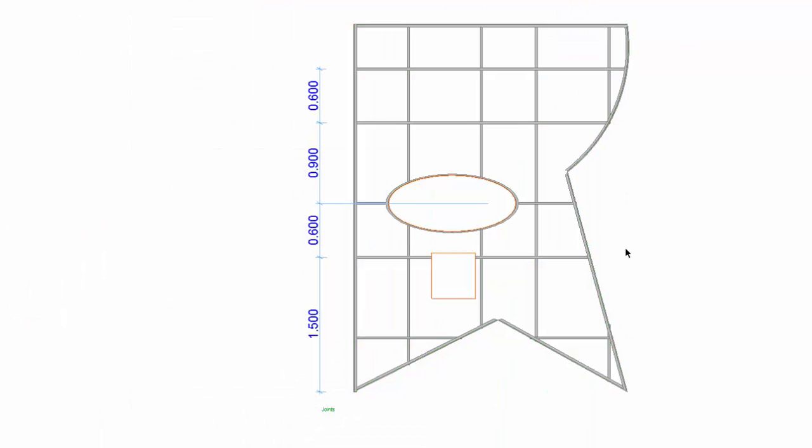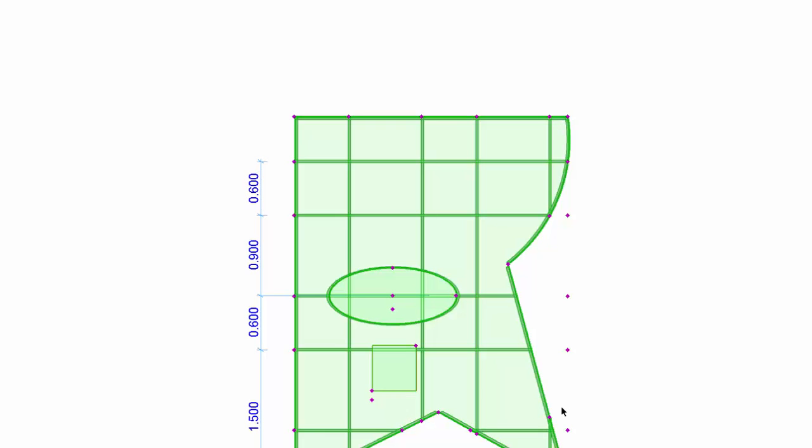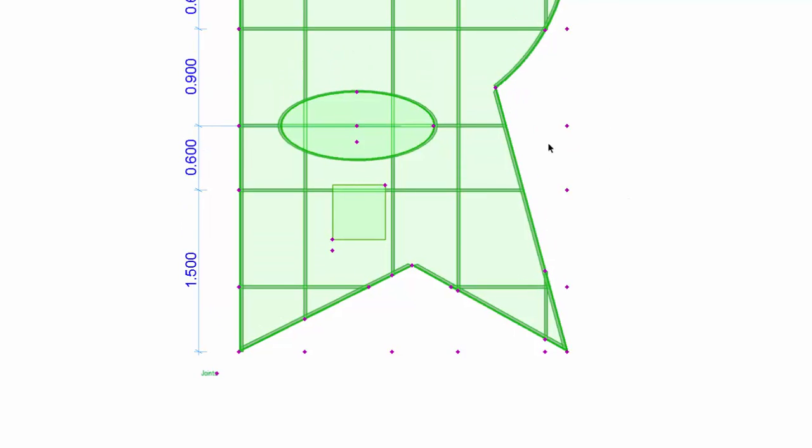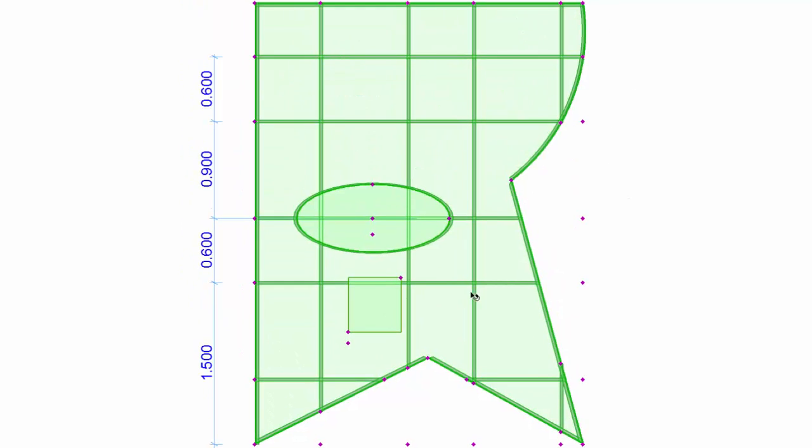Okay, so what was happening with that issue, this is something that you have to be wary of, is when a joint is running into two edges at the same time, it basically computes a cut twice at the same value, and that obviously causes problems. I'll have to try and work out something to work around that, because there may be instances where that is part of the design, but for now, if you get an error and that's happening, then that's probably what your error is.